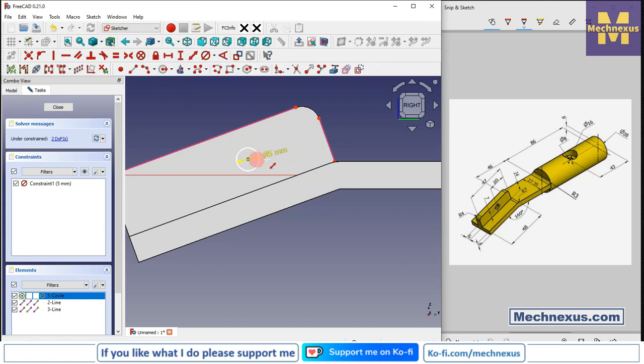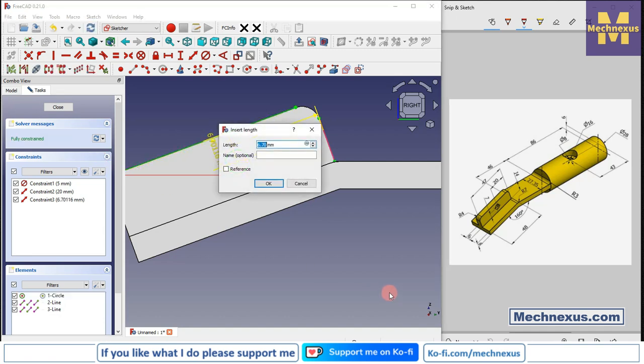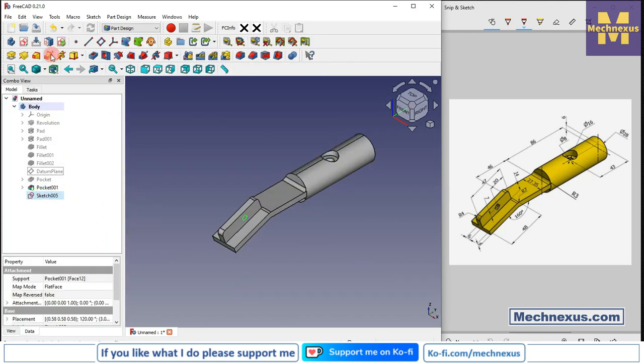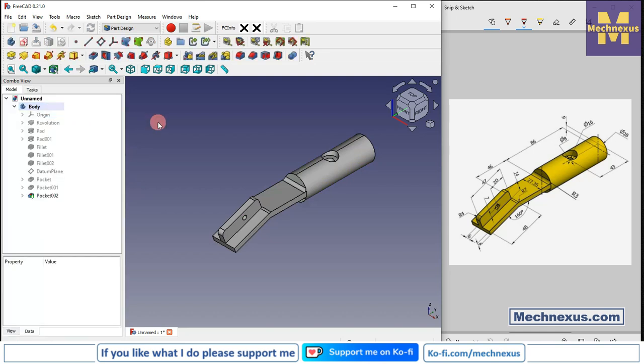and select dimension, select this point and this point, this line, and provide it a dimension of 20 and select this point and this line and provide the dimension of 7 mm. So our sketch is fully constrained. Select the sketch and click on extrude cut, and from here say it through all, say OK.